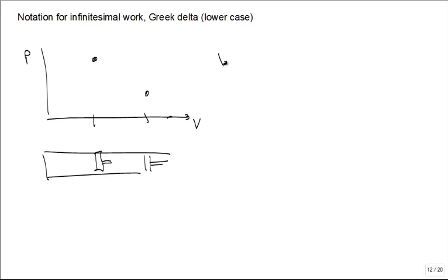I want you to calculate the work done by the gas as it pushed back that face of the piston, as the gas expanded. You'd say, Professor, I only know how to do the work of a force on a mass or a force on an object. True? You say, Professor, I can calculate the work if it's F dx. True? Okay, do this. If I multiply this by A and this by A, what is the force on the face of that piston per unit area of that piston? Pressure. This is the pressure.